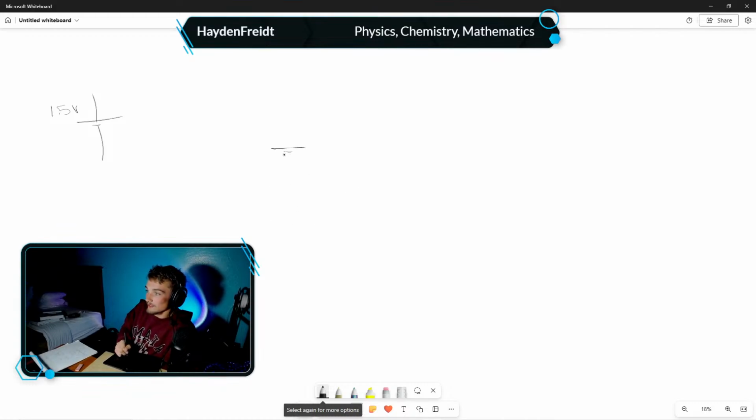But again, the battery is going to have a large plate on top of a small plate, large plate on top of a small plate. The small plates are essentially the negatives. So it's like we have these cells in series, right? And when you put things in series, even if you put batteries in series, you're going to get an addition or a sum of voltage. So if I had two 9-volt batteries in series, I'm going to have 18 volts.